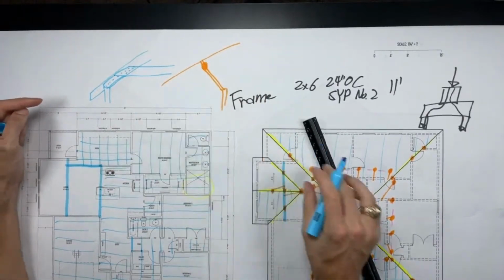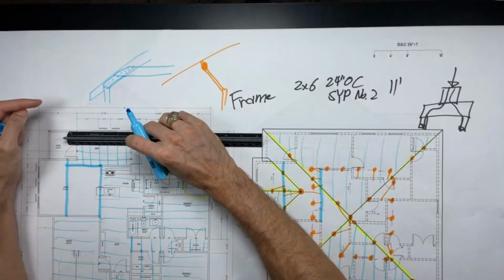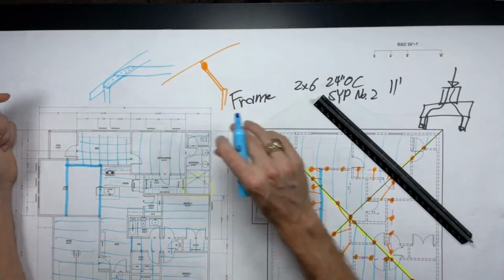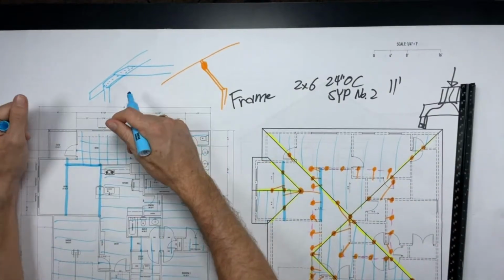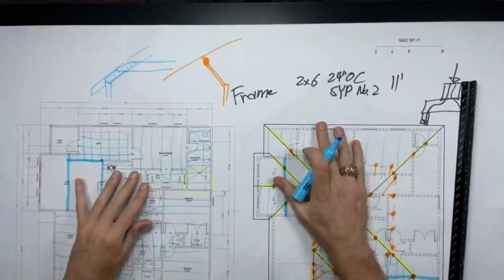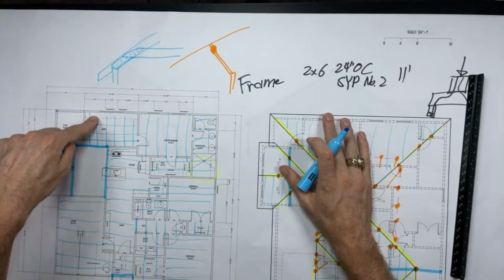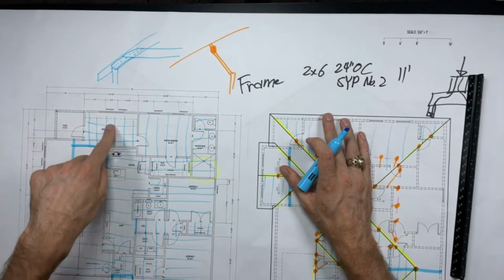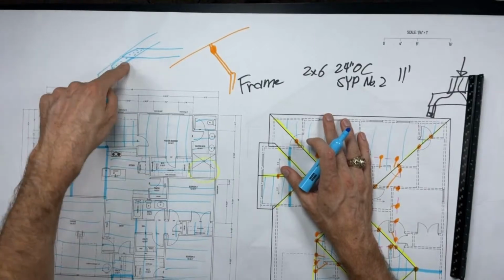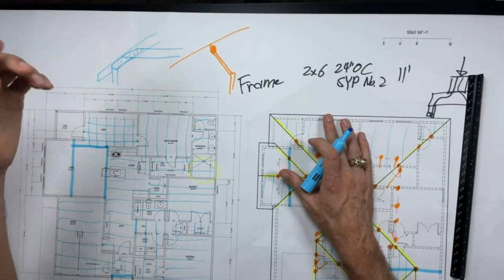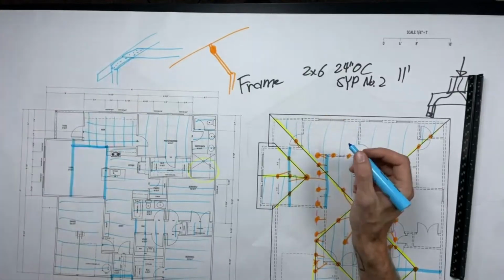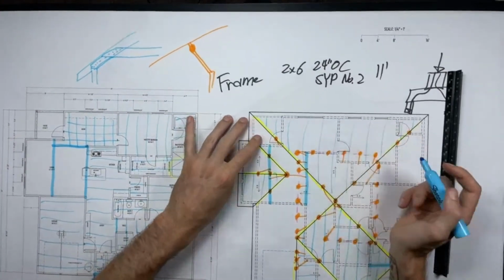And also, that's kind of an annoyingly long span that's closer to 14 feet, and I want to avoid that. So that's a shorter span. That takes care of it. Now, red flag, whenever you see that, it means you're going to load your rafters more than you think you are. The extra ceiling weight from here is being pushed and set on the rafters with this thing. And yes, there's a block sort of also catching the weight, but there's more load going on the rafters than you think.